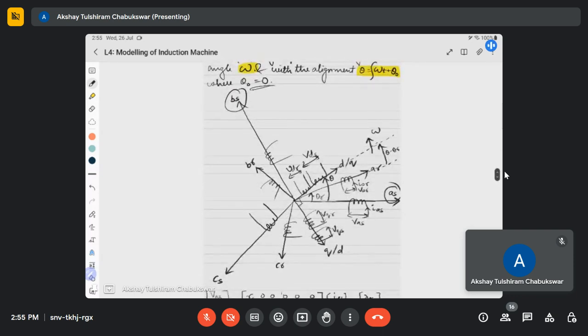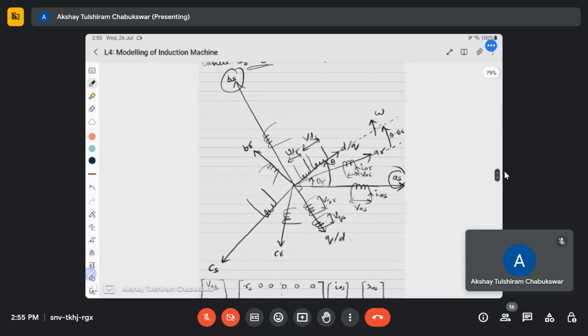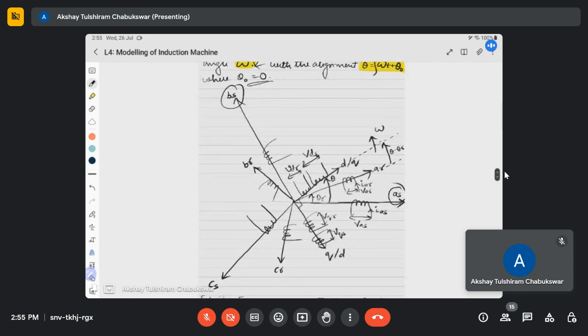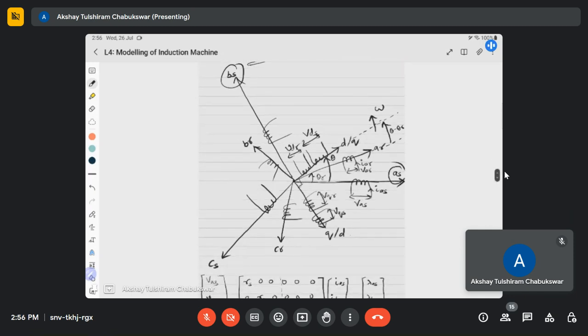As I mentioned in the last lecture, the stator of an induction motor has distributed windings. Distributed means the stator construction includes parallel slots, and inside those slots we keep bunches of conductors, and then we electrically connect all these conductors in such a way that on the panel of the induction machine we have six terminals. Those six terminals we can connect in a star connection or in a delta connection. There are different benefits of using star and delta connections. If you want more starting torque, or less current or more current,